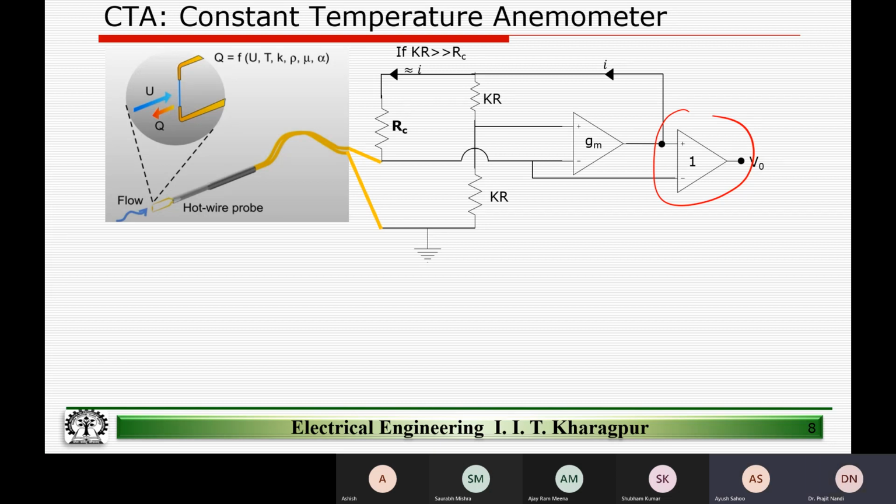Excuse me, sir. Hello. Yes. Ayush. But in the right part of the circuit, if the op amp is virtually shorted, then we see that RC is shorted. No, RC is not shorted. Please look at this. This is VB. So forget that. There is no feedback with this. This is an open loop amplifier. Oh, okay. Sorry. From here, right? Yes, sir. Got it. Okay, we'll discuss this again tomorrow.